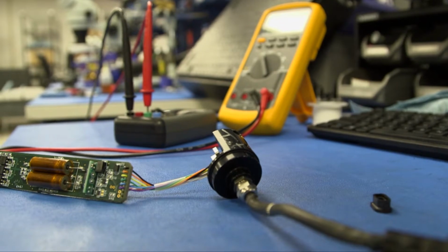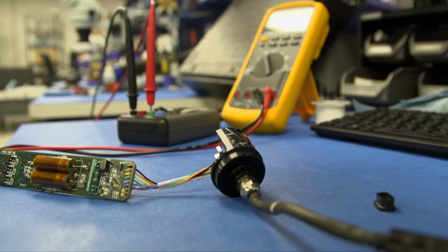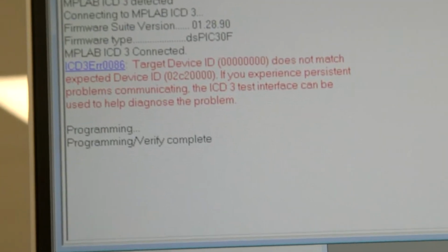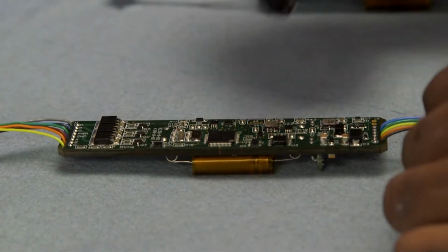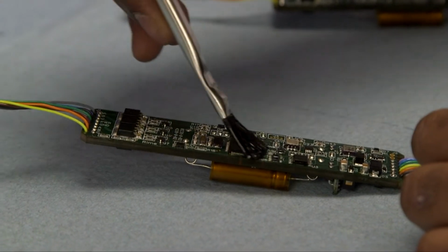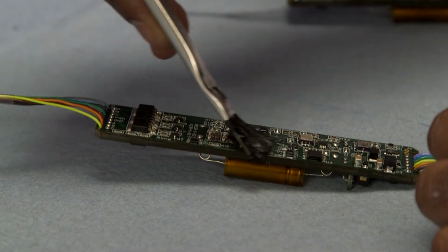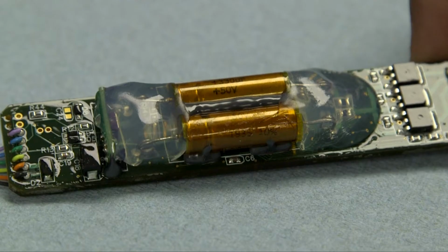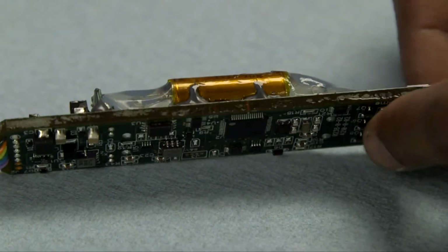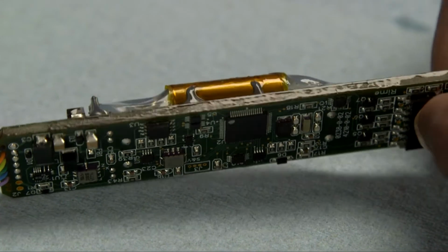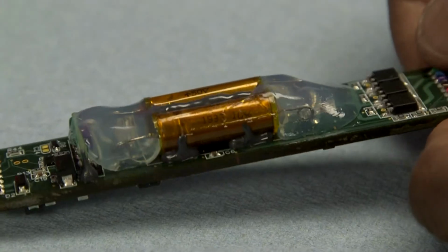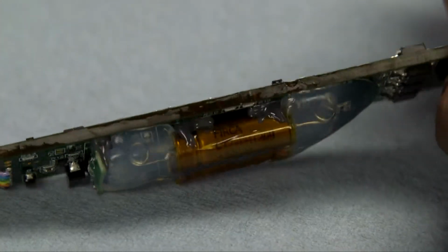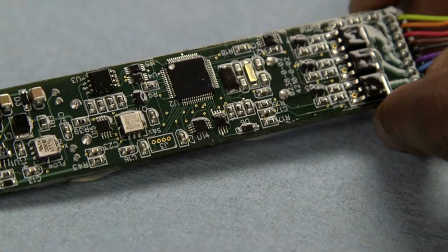The harnessed board is now connected to our power supply and it is programmed with the firmware. The programmed board is conformally coated. The coated board is allowed to dry for several hours to adhere all the components to the board. After the conformal coating step, specific components on the board are epoxied down and rubber is added in select areas to maximize vibration protection and mechanical ruggedness.